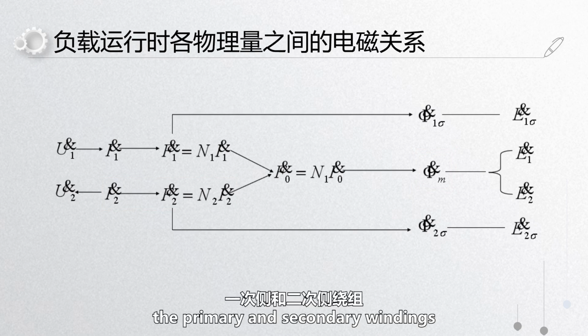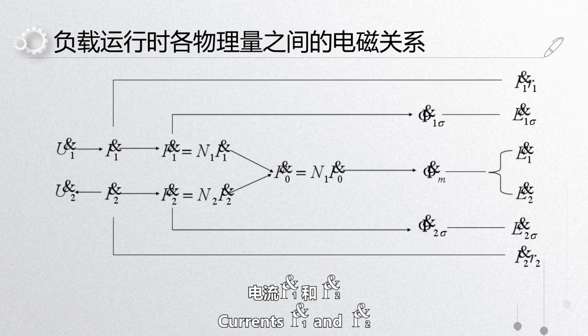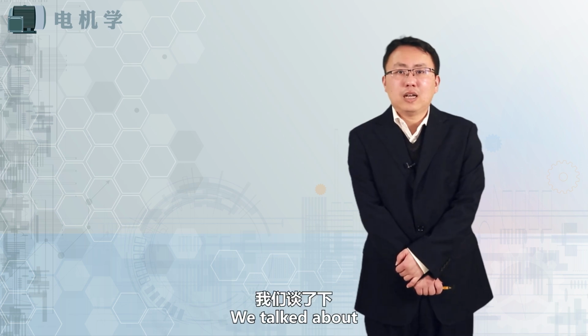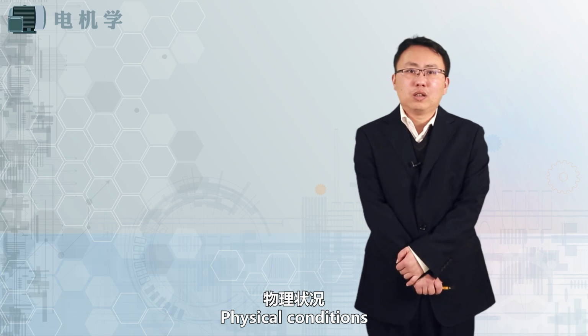Additionally, the primary and secondary winding currents I1 and I2 will also produce voltage drops in their respective winding resistances, I1R1 and I2R2. Earlier, we talked about the physical conditions of transformers under load operation.